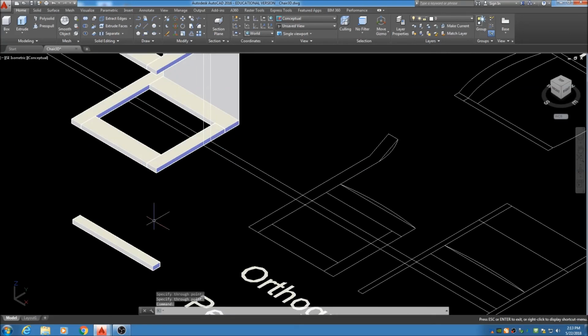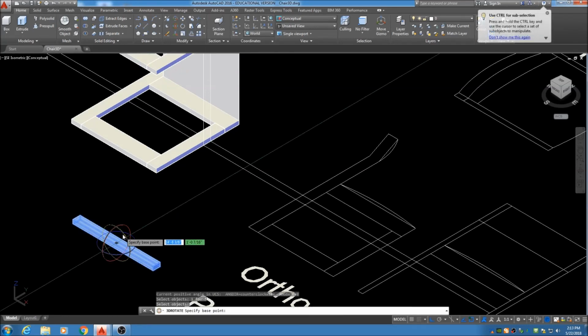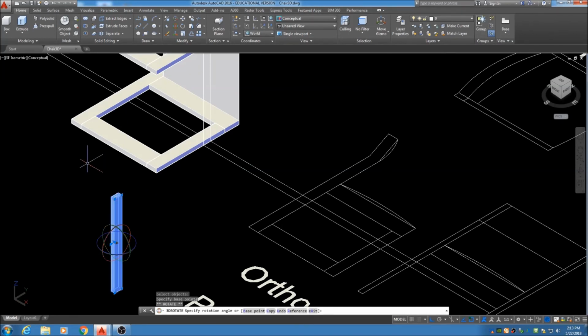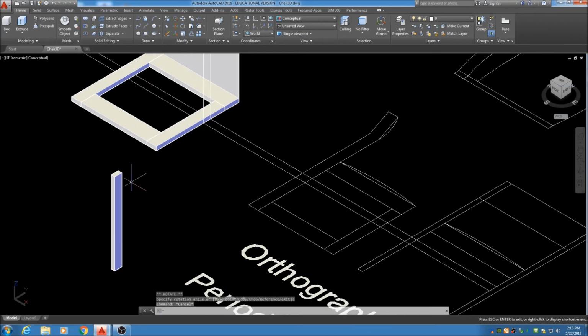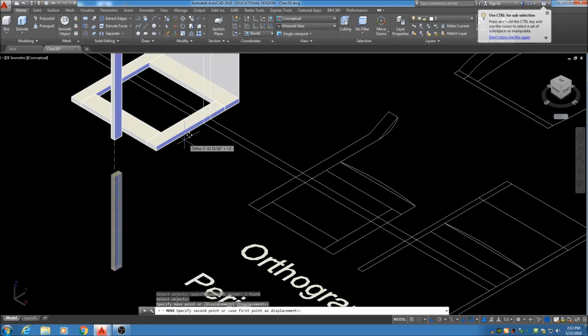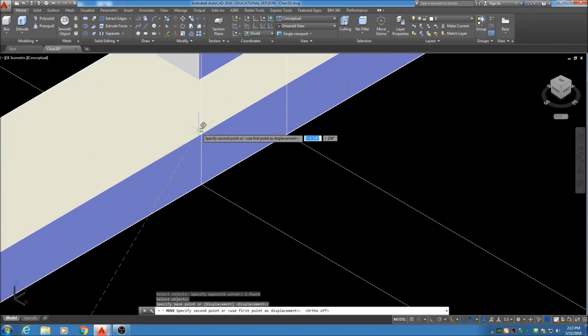Great. All right, now let's stand this up on its end. So we'll get the old rotate 3D tool. Make sure you're on the proper axis, click it. And because I have ortho on, you get these nice 90-degree angles. Don't have to even punch in the angle. Move tool and grab it from here and drop it there. Got to see where it meets up.